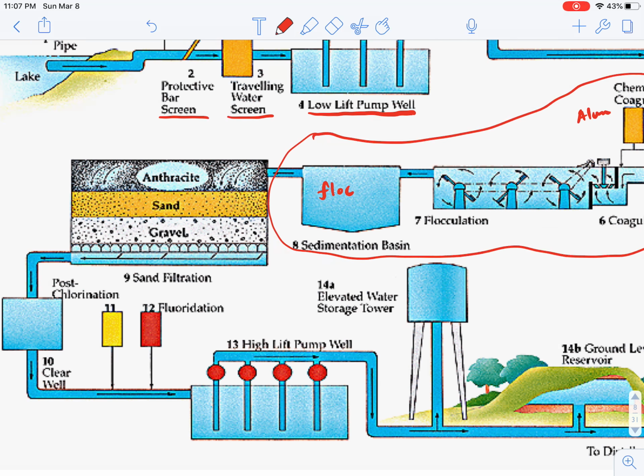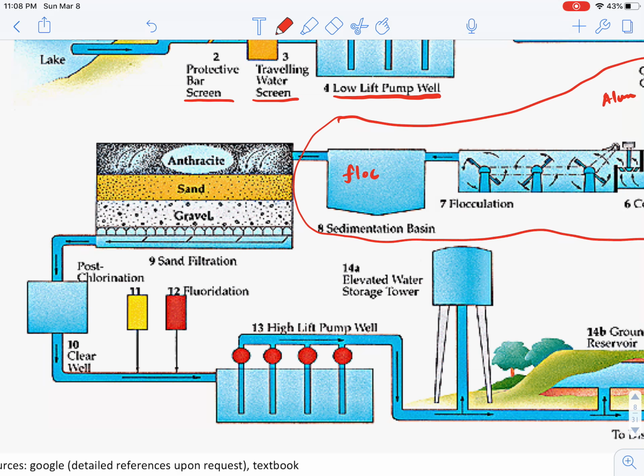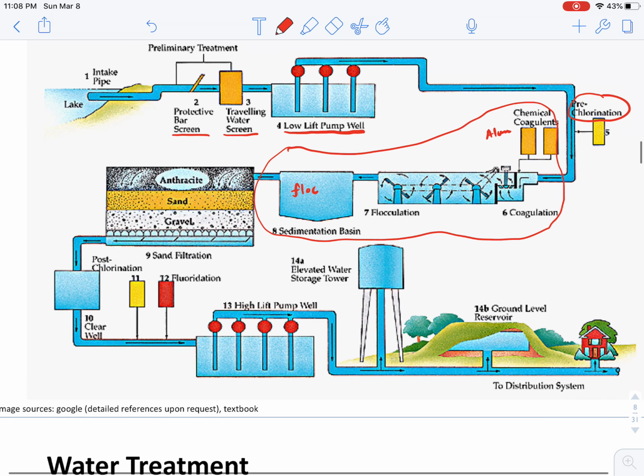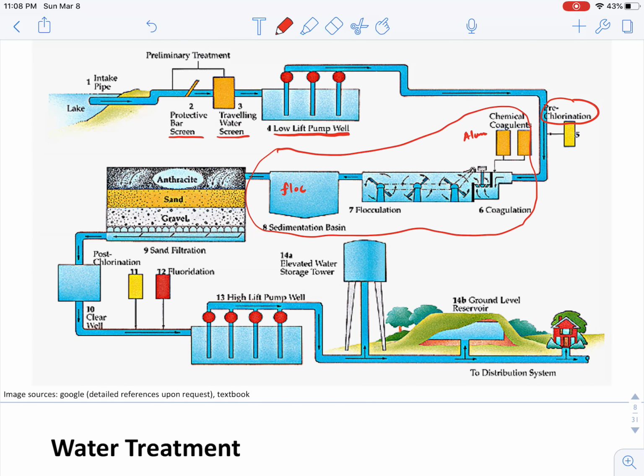And then at the top of this basin here, we'll get relatively cleaner water. And then we can feed this water through the sand filtration. So as I have introduced, if the water quality is already clean enough, we can probably just ignore these previous steps and directly feed it into the sand filtration. But unfortunately, for most areas, for water treatment, we have to go through these complex water treatment processes because the water is not directly potable.